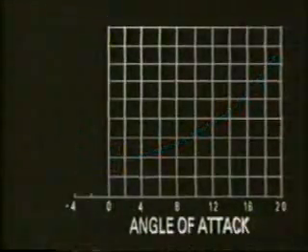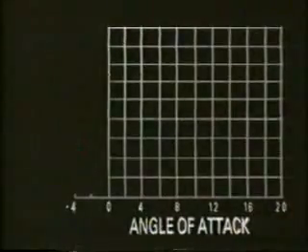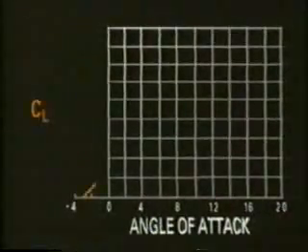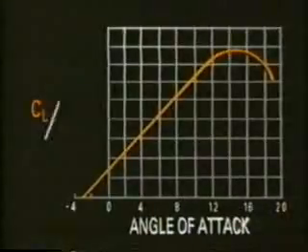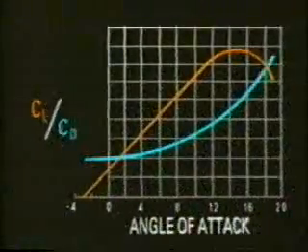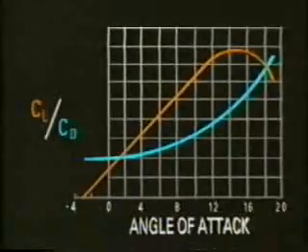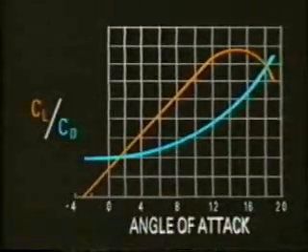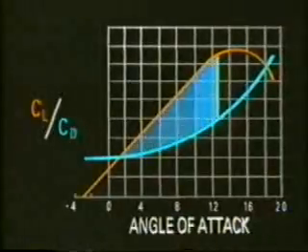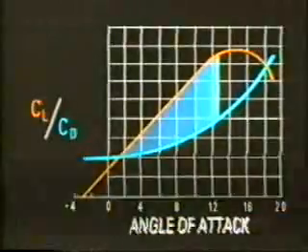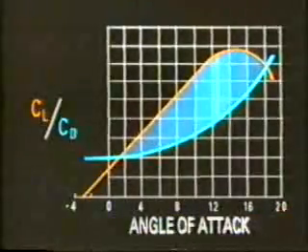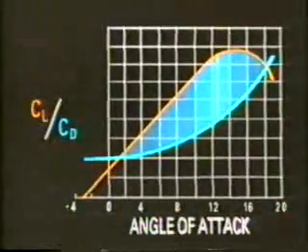Although the lift and drag curves portray their relationships to angle of attack, it's easier to understand performance considerations when the two curves are plotted together and the lift-to-drag ratio is examined. You can now see that as you increase the angle of attack, the lift-to-drag ratio increases to a maximum, and then decreases at the higher lift coefficients and angles of attack.